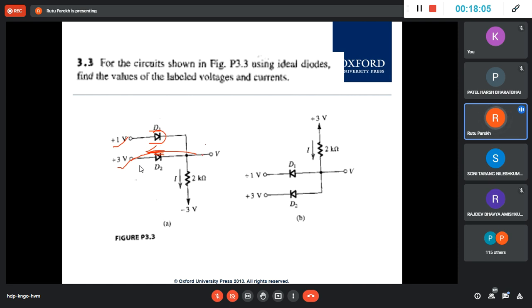That way it will short this point here. And as you go to +3, so this will be now 3 volt. And the V1 will be blocked. So now this is 1 volt, this is 3 volt, and then this will be reverse biased. You are right. But the stronger voltage will appear because if you think graphically, in a fraction of second, it will start conducting earlier.